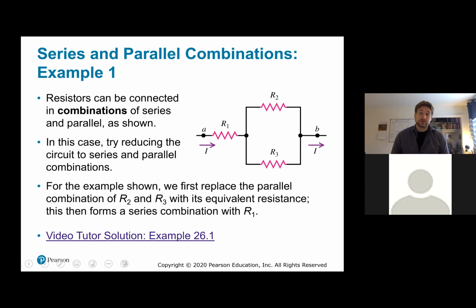all right, what if we have both? Series and parallel. Well, R2 and R3 are in parallel. We know that because this point and this point are the sort of terminal locations for this path and for this path. It's the same point though, so the potential difference across them is equal. If the potential difference across 2 resistors is equal, then they're in parallel. That's kind of what that means. So R2 and R3 are in parallel.